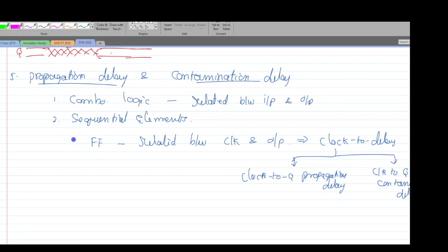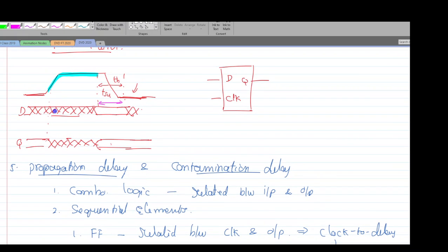So first we spoke about this flip-flop, and now let me discuss the propagation delay and the contamination delay with respect to the latch circuit. As we know, the latch circuit is a level sensitive circuit, and because of that, any change of data happening inside can also affect your output. So there is a possibility that D can affect your output, or if you are holding the data constant well before the rising edge of this signal, then the output would change only because of the clock.